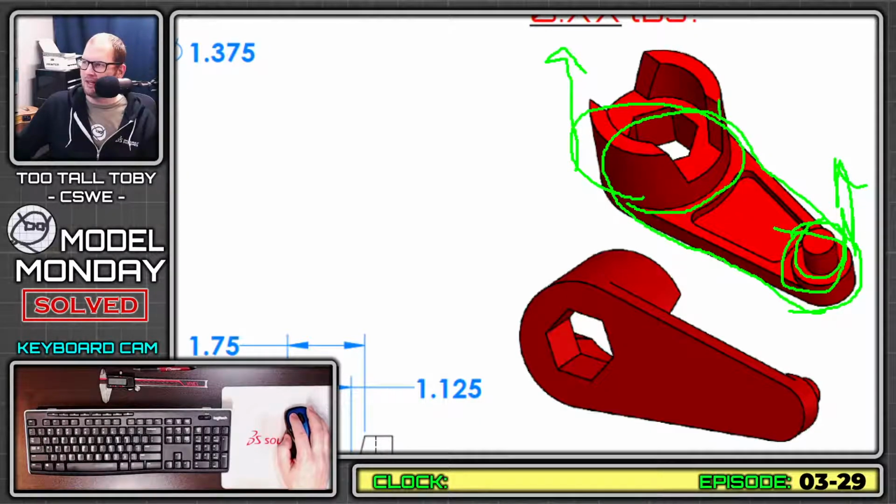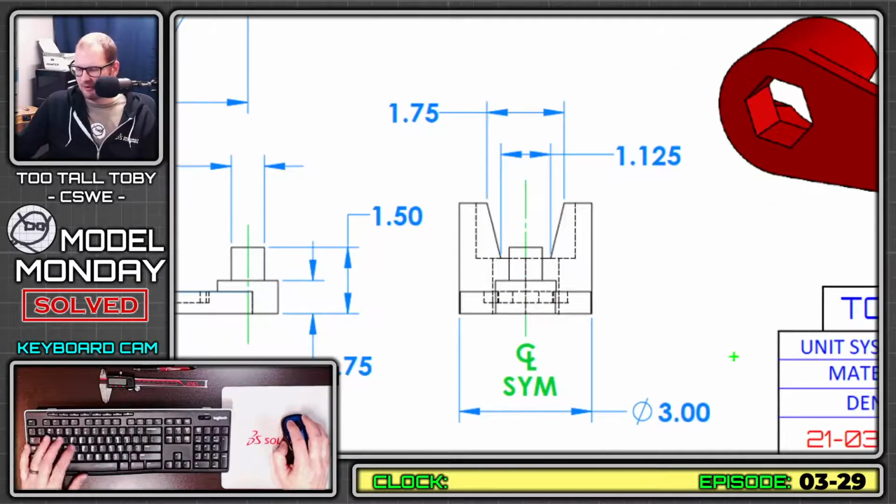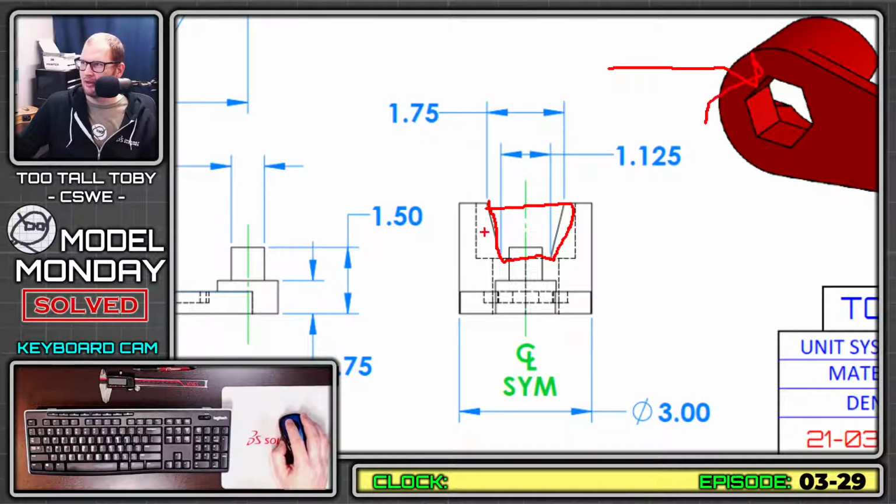Next thing is I'm going to need to create this cutaway. And this cutaway looks kind of weird. It looks almost like things are drafted, but there's no draft on this, not really. I mean, there's this angled region down here, but it's not traditionally drafted. So I just need to create this cutaway, blast that through that face. And then I should be ready to move on and do the final feature, which will probably be the hex. That final cut extrude feature at the bottom.